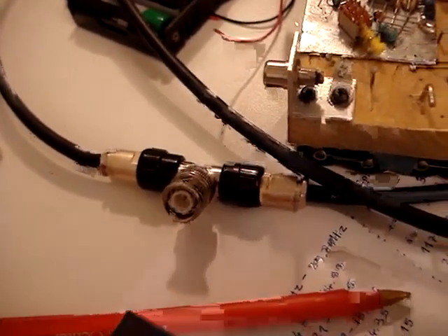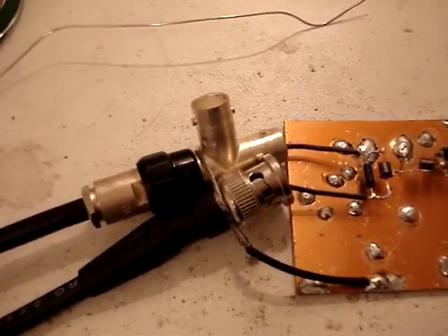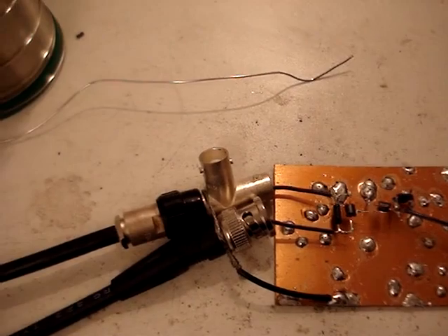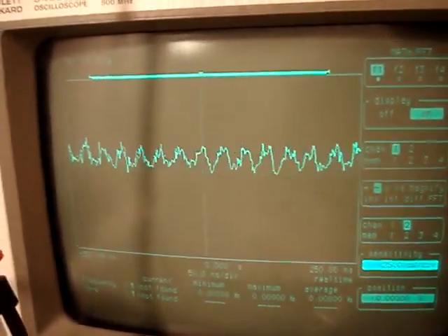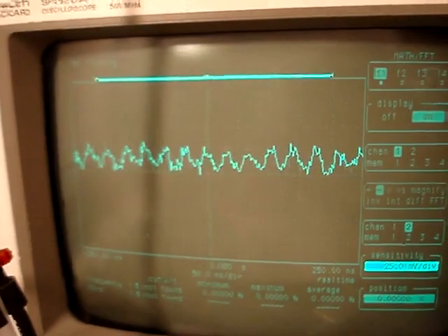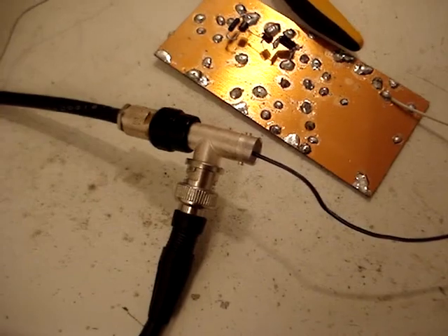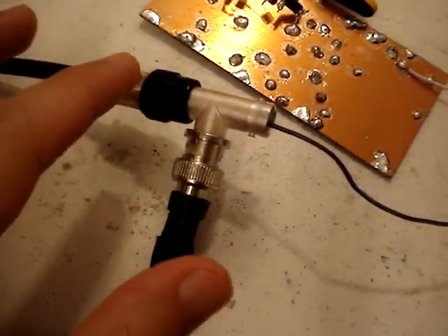It's composed of two smaller pieces of cable, and also there are differences in the end connectors. So all this might introduce some phase or even some amplitude difference depending on the loss of these things. But 25 millivolts difference is quite a small difference for most of our QRP projects. An interesting thing is that when I connect the two cables together,